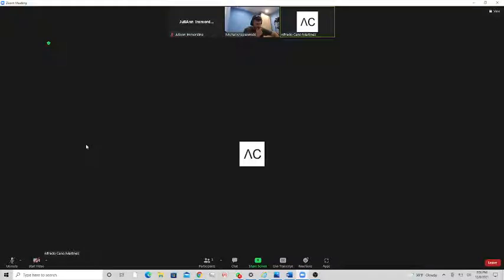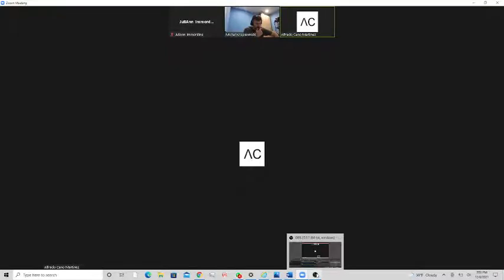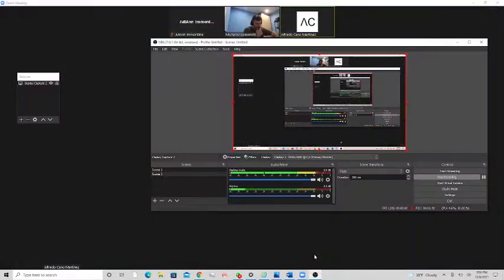So it wouldn't really make sense to say that the KP is just for position output, even though the confusion may arise. You could argue that it stands for position because in most cases you use the KP gain in a circuit where you feed back the position. But it is really not related to position. It is related to the proportional gain.